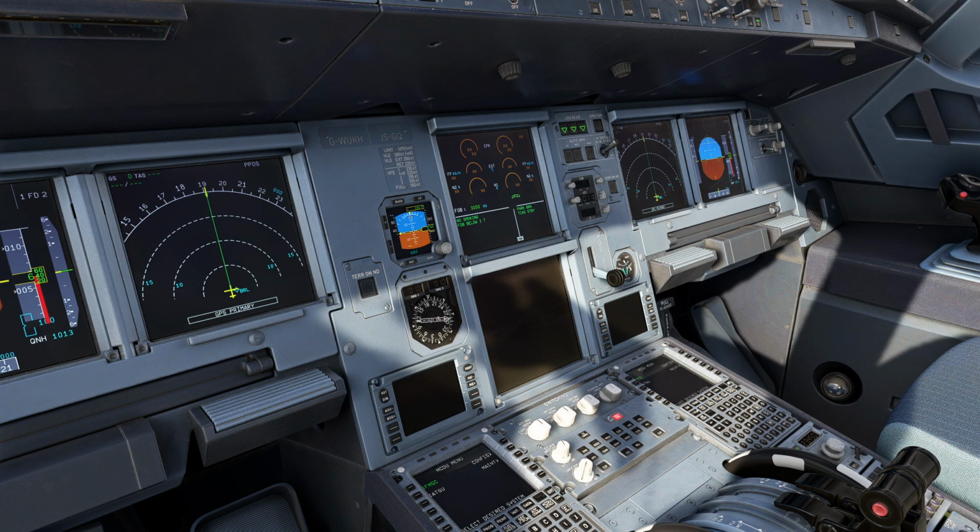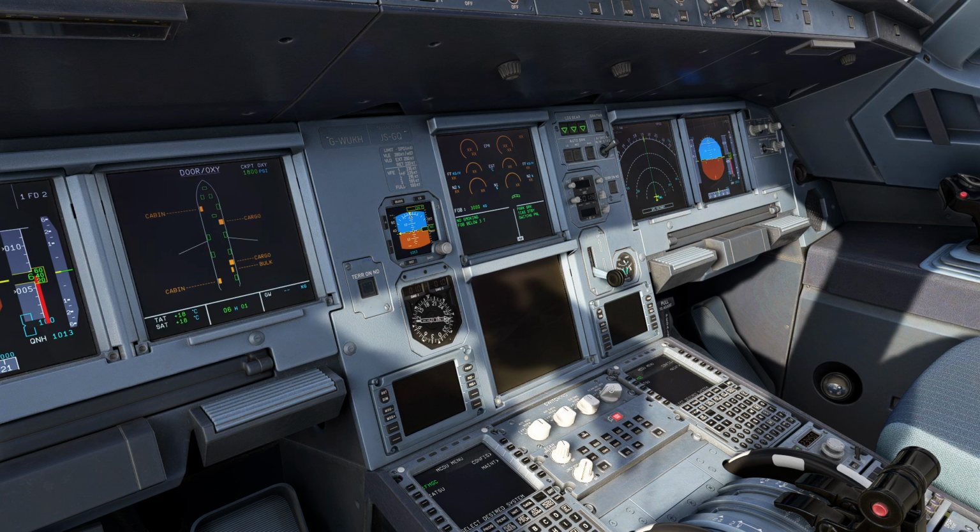If the lower ECAM display fails or is switched off, the flight crew can display the system status page by using the ECAM ND transfer on the switching panel to display on navigation display. As before, when we select the ECAM ND transfer switch to, for example, captain side, we can see the system display on navigation display. It is a perfect setup during cruise and low workload condition.